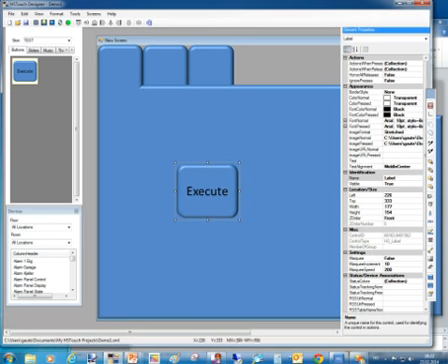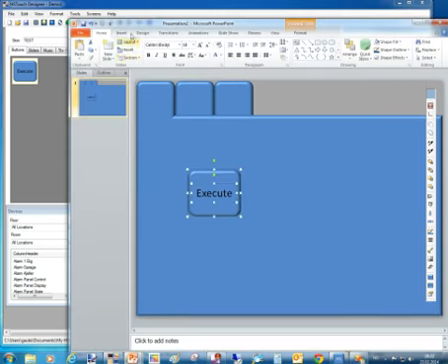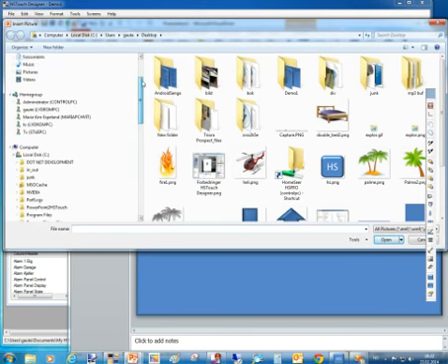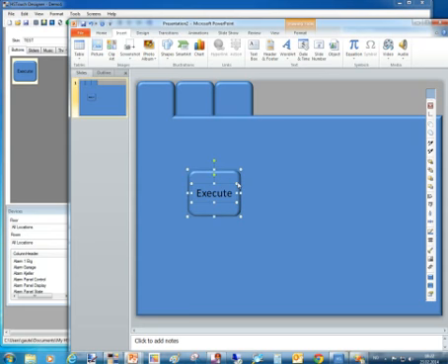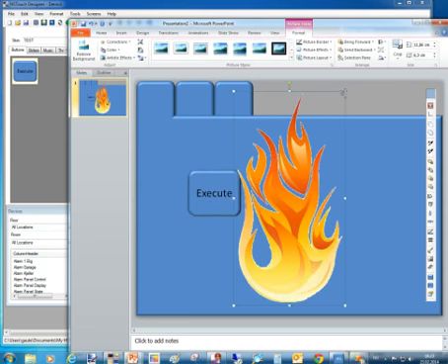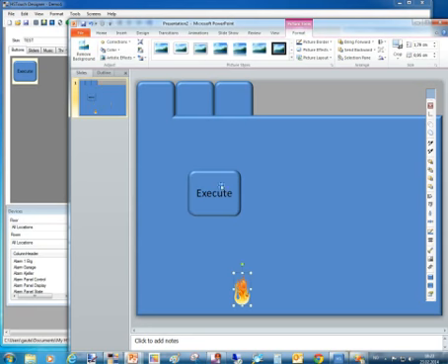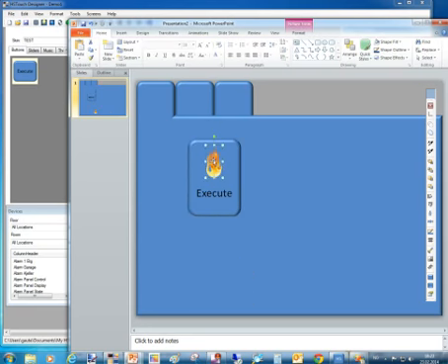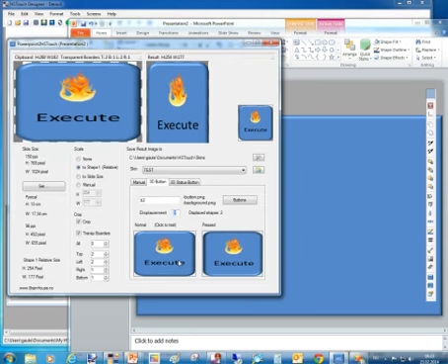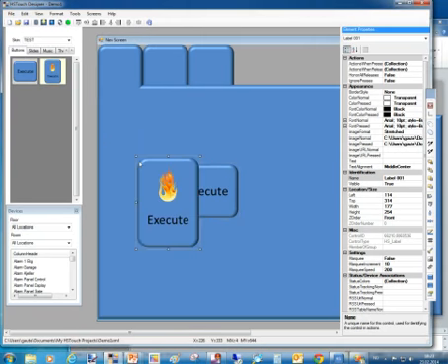If we want some graphic on that button also, we can take it some graphic. Let's take this one. Scale it down. Something like this. Then it's important, select the button first, then the other graphics. Then it will immediately know which is the button and move the others accordingly to simulate a push of a button. So this would be B3, store, in and out of the button, take it down here and test it.